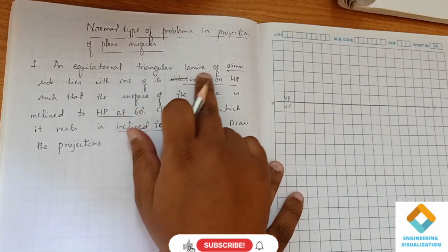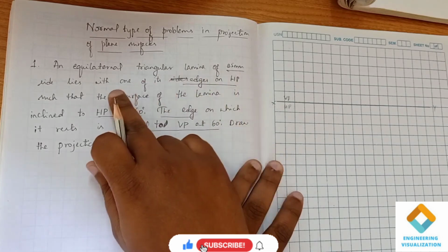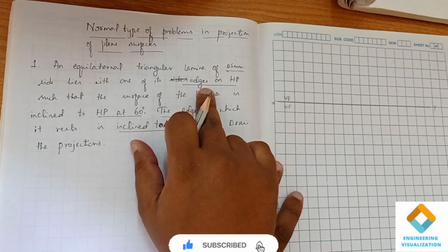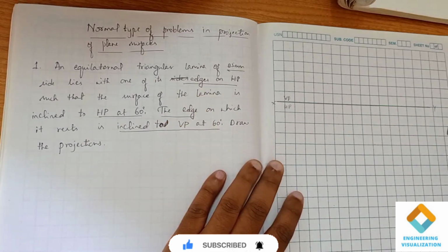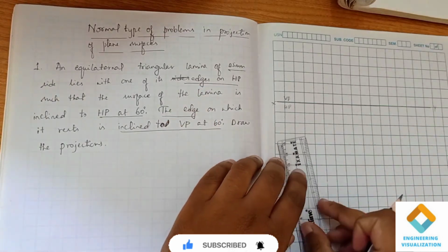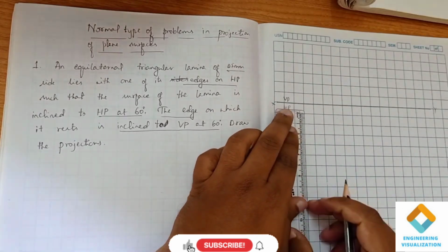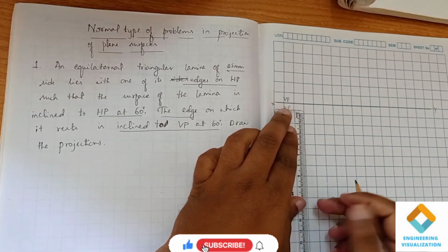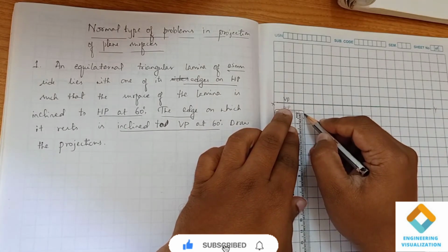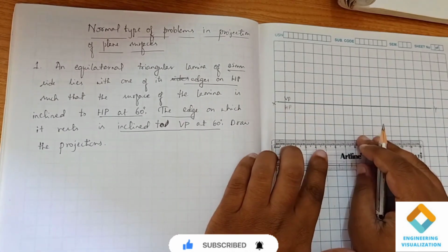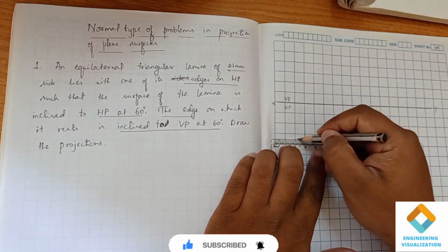Okay, so now you see the question. Our equilateral triangular lamina of 25 mm is resting on the HP with respect to the edge. We know how to construct a triangle with respect to the edge. Okay, so the dimension here is 25. I'll be measuring 2.5 boxes, that is 25 mm. I'll be showing the dimensions on one side.